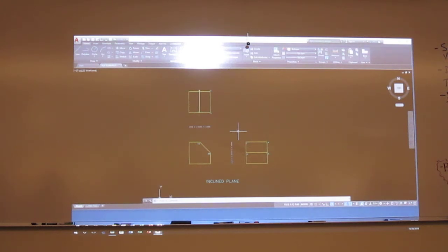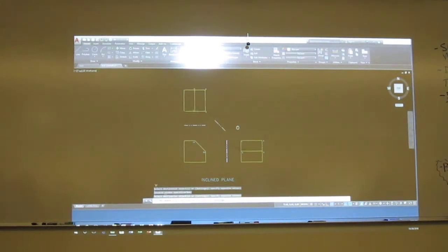Now, once we do that, we have to create that identical fold line for our auxiliary view. You've got the edge view sitting right here. So we now know the angle, because we want to come in perpendicular to this, right? So let's do an offset in this case. I think 4 works pretty well for this one, and I'm going to put it right there. So just offset that one, and do a 3 or a 4 offset. So you should have 3 lines on your drawing now.